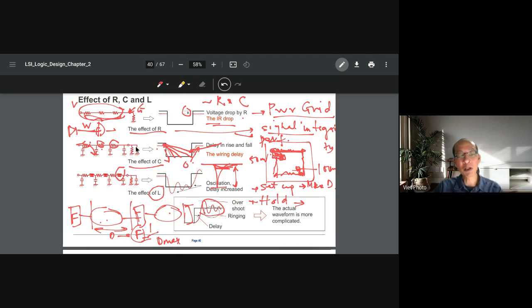But for the lower layers, it is used for routing to connect the logic gates. It will be crowded, so we cannot make the wire as wide as we want. We just have 2x or 3x maximum. So with that, we can reduce the width, and limit this one. Another way to reduce the resistance is to buffer it. When we have a long wire, we will buffer it.